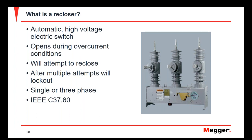Now, it's not going to just continually open and close and open and close. It has a maximum number of close attempts. Once it reaches that number, whether it be 2, 3, maybe 4 times for that recloser, the recloser is going to lock out and not attempt to close again. It's going to consider that fault a permanent fault and lock out. These reclosers can be found in both single and 3-phase forms. We're going to talk a little bit more about that in a minute, and the applications of those different types of reclosers.